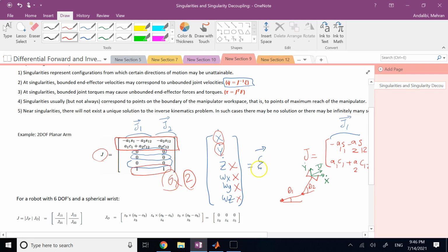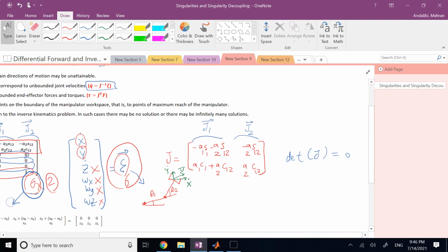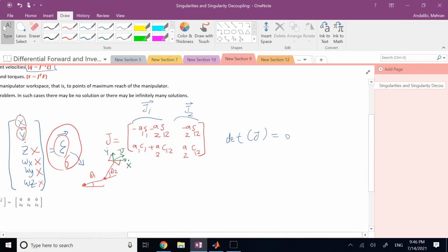And that's because this zeta at most can move in 6 directions. So you clearly see that the degrees of freedom in zeta is directly related to what? To the rank of J. If the rank drops in J, it means the degrees of freedom along which zeta can move or rotate drops, and that is called singularity. Okay, so you see I'm using all sorts of different languages to explain this notion to you. Good. So at singularities you lose rank.